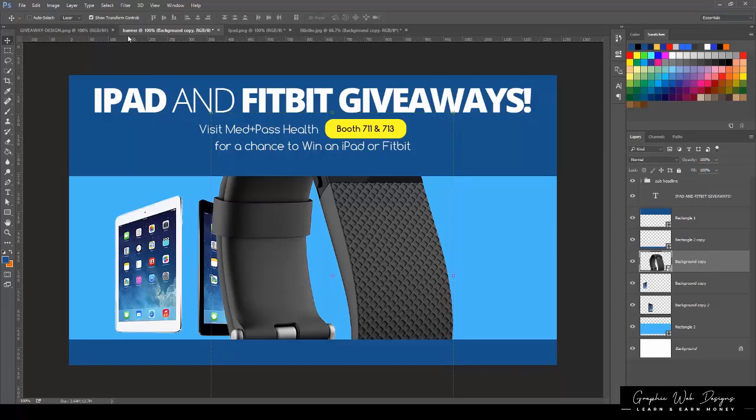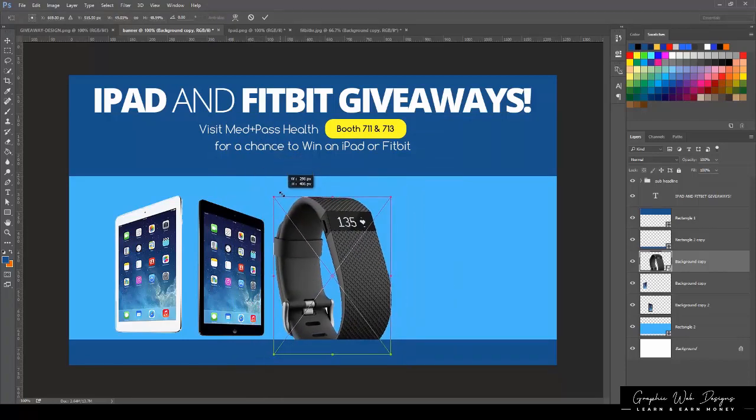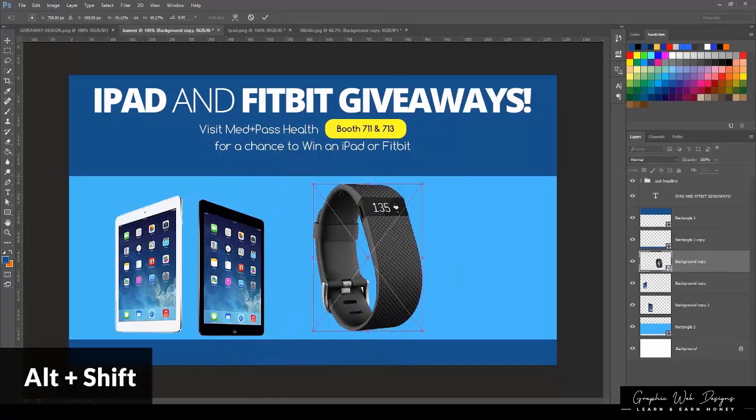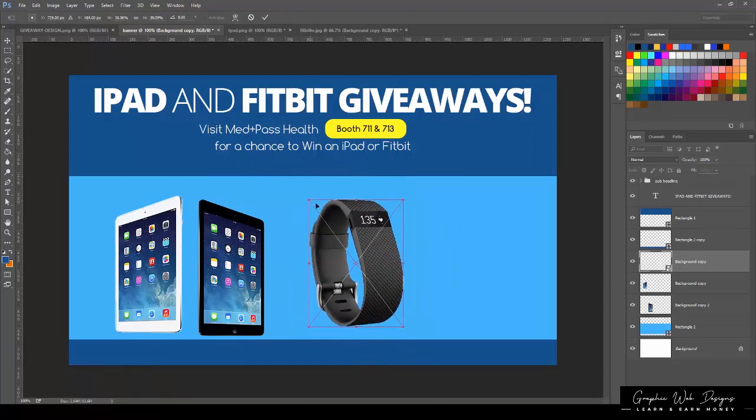Now make sure you have Show Transform Controls checked in the tool's control panel, then hold the shift key. Never resize an image from the side, otherwise it's going to distort the image. Resize it from the corners. Hold the shift key, then resize it. You can add the Alt key to it. That will make it a little bit faster for you because it's going to resize it from both edges. I'm going to bring in the back the same way I did the front.